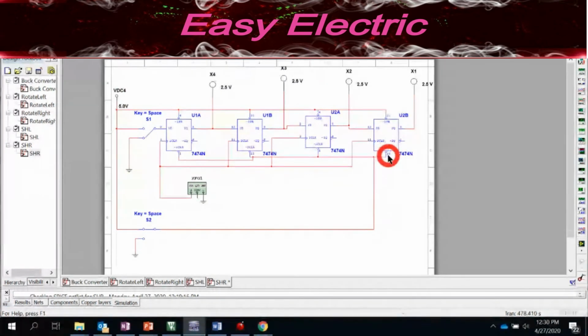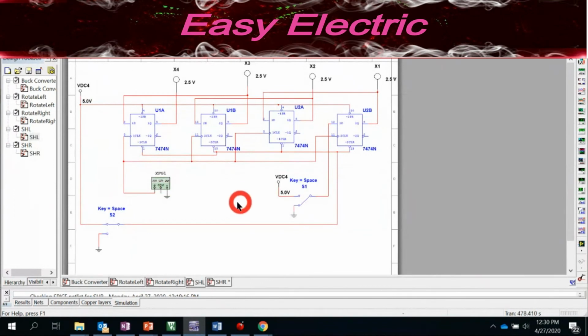So the clear, CLR, is these pins, connected all of them to each other and connected to one switch, which we call the initial pin in our design, right? Just for a short time, whenever I want to start to work, I put that at 0, then back to 1. This is what we need to do. Then see what else we have. This is shift right. We need to check shift left, which is the same thing, same explanation.